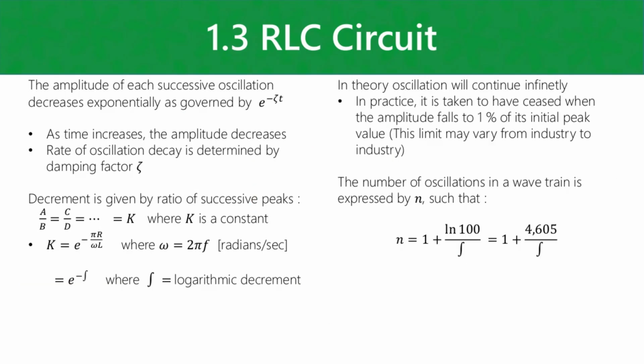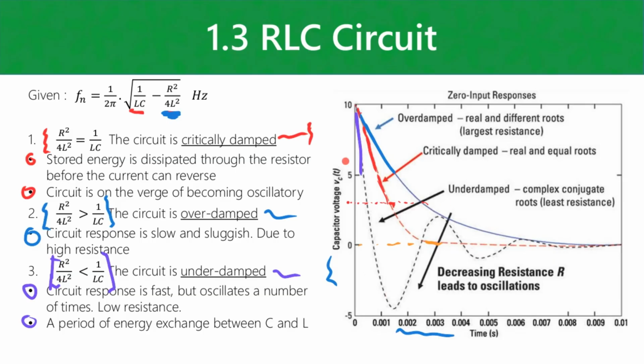Okay, so one of the things that we can see here, especially with an underdamped system, I hope you will notice, is that the peaks of the oscillations decrease at an exponential rate. Even if you run this through a rectifier, for instance, so that you make the wave a positive wave, you will see that these waveforms form an exponential curve with the peaks.